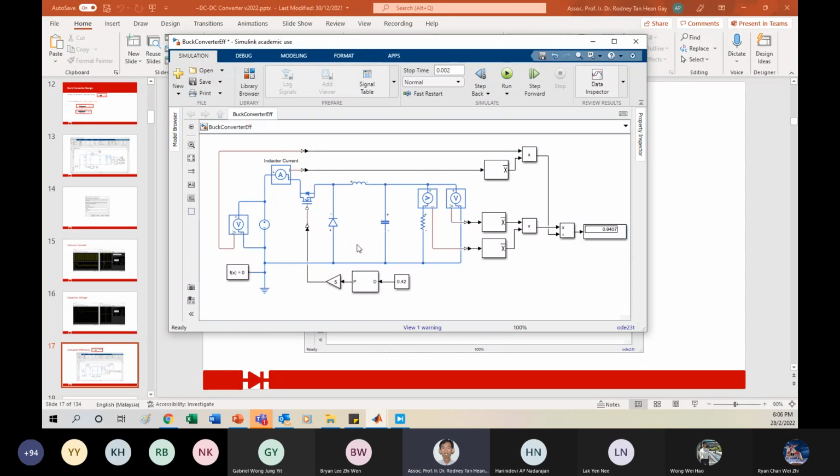Of course, here we don't see the problem with the recovery, but it does give you a very significant efficiency compared to the linear regulator, right? So again, as I said, the reason we need to use this switching frequency is that a linear regulator does not have any switching frequency. It's fixed DC. So that is the advantage of using a buck topology.